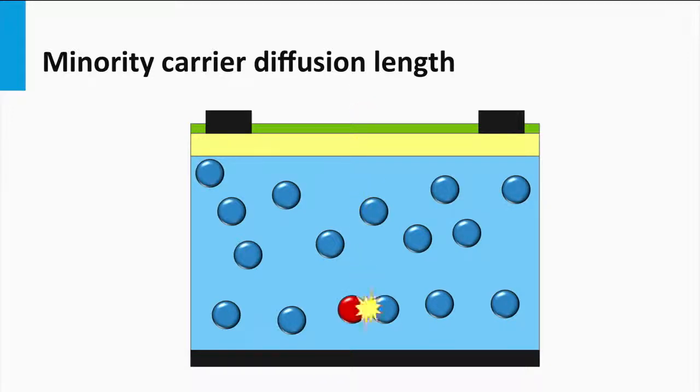Let's consider photons that would penetrate far into the absorber layer before they are being absorbed. We want these charge carriers to be separated at the p-n junction or the back contact. But let's assume that these charge carriers are excited at a depth deeper than the typical diffusion length. The excited charge carriers recombine within the typical diffusion length before arriving at the p-n junction.